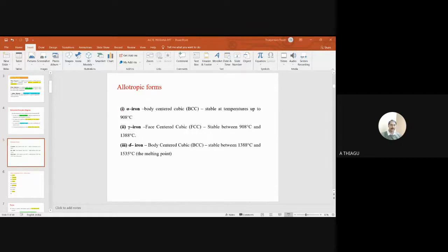Once the sample is allowed to cool, the microstructure modification will happen. So experimentally we have to investigate the microstructure, what transformation is produced under the slow cooling process. This particular information helps to find better mechanical properties. So this is the microstructure we have obtained. In all the cases we have to say it is the form of pearlite only.